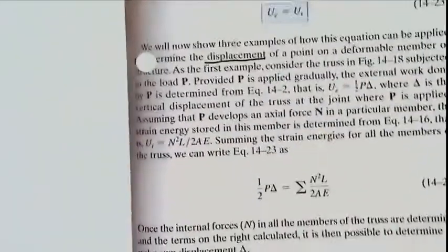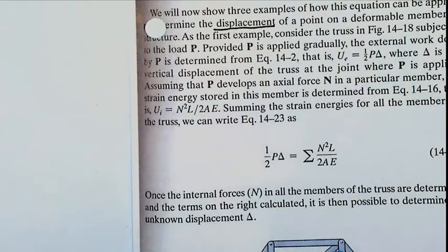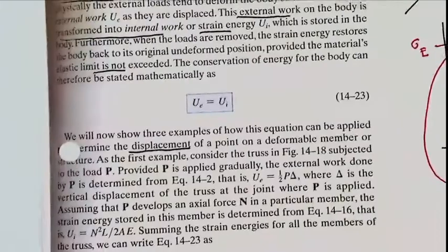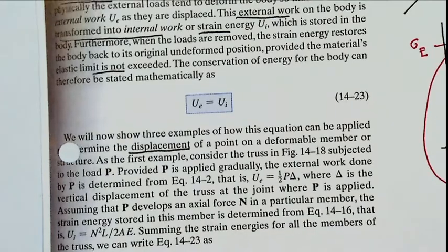So, for example, in case of the bars, this load P works on displacement delta, okay? Now this displacement delta transforms into the energies of these bars, 1, 2, 3, 4, 5, 6, 7, 8, 9 bars, and energy in each equals N axial force squared times associated length divided by 2 times cross-sectional area and modulus of elasticity that we obtained last time.